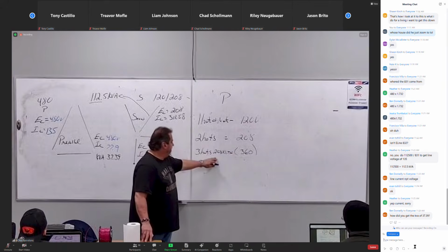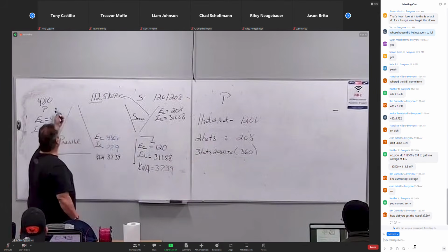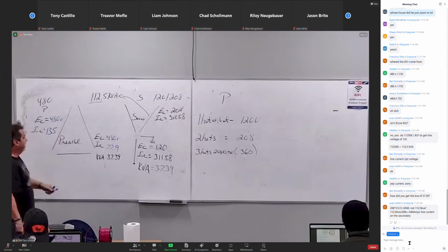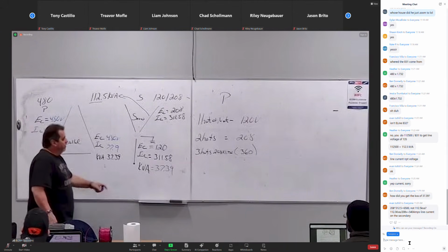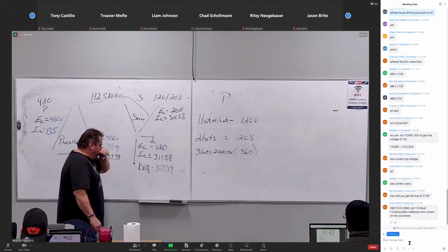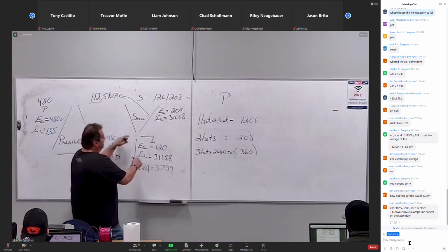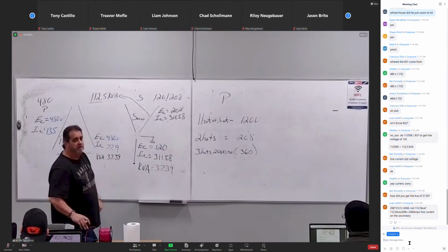So we just use this as 208 3-phase, 208 single phase, 120 volt. Same thing here. 480 volt 3-phase. 2 hots would be 480 volt single phase. 3 hots would be that. When I have 3 hots, my voltage is going to go up. So that's why each coil is worth 120. Yes. Wow. So 120 to 120, you're thinking 240, but I've got influence from here. But in a series circuit, remember, voltage doesn't stay the same, current does. Hot to hot, 208. Hot to hot to hot, it's actually 360 volts if you add a third leg on the meter, but you don't.